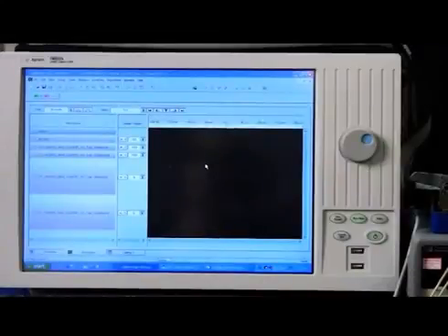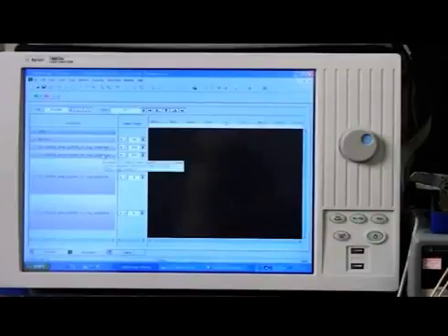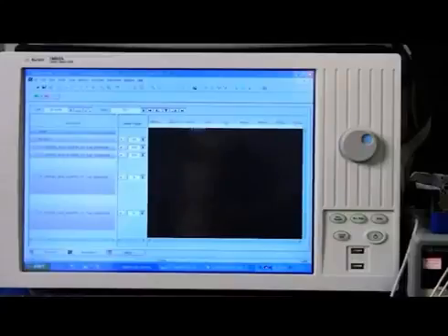So let's first take a look at the filtered IQ digital signals in this design using a 16800 series logic analyzer that's also running the VSA software. So here we have a couple labels. This is the I data, the Q data, and then I also have the I and Q data in a chart mode. So I'm going to hit run and we'll capture the signals.